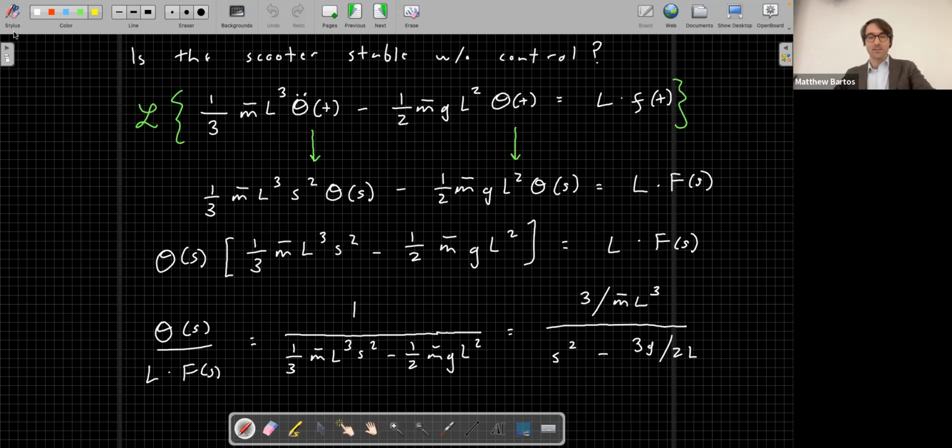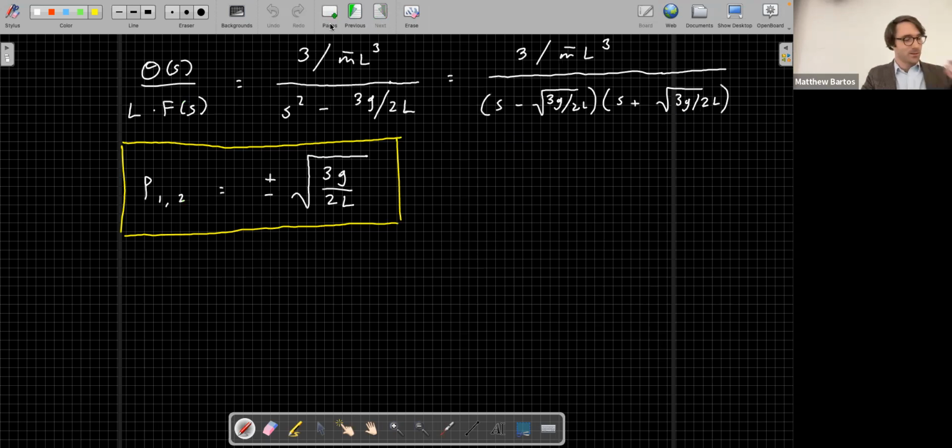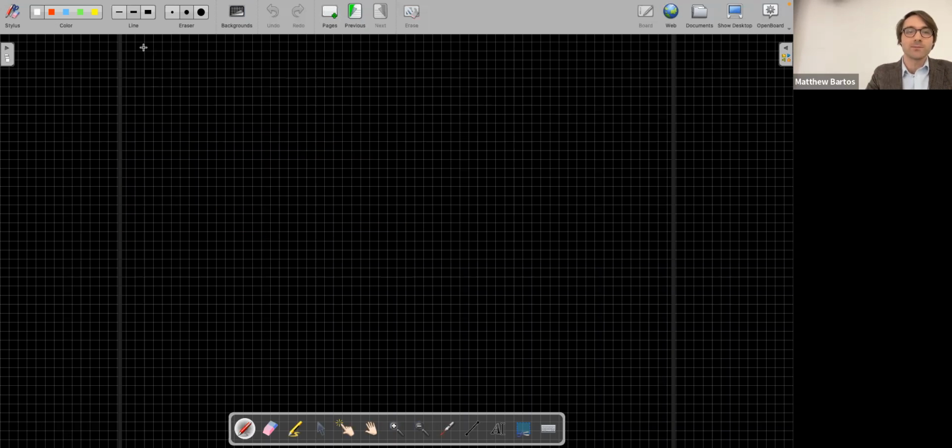So perhaps the simplest way, the first thing we might think of, if we want to create a control rule that stabilizes the system, is to simply look at the angle, its deviation from the center, and apply a countervailing force that's proportional to our deviation from the center. That sounds pretty reasonable, right? That is what is called proportional control.